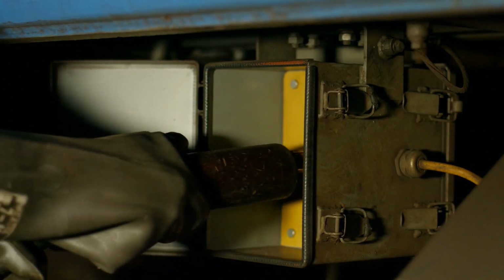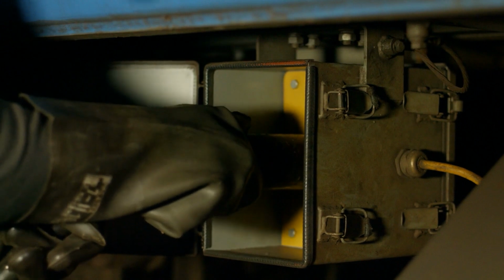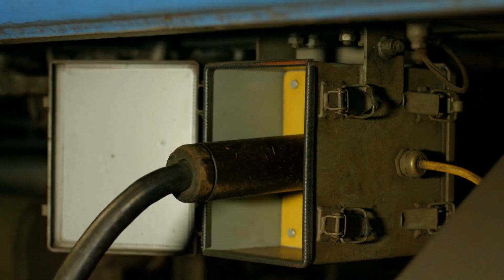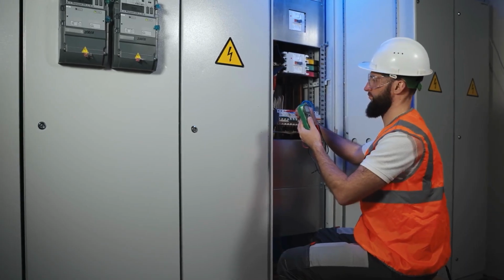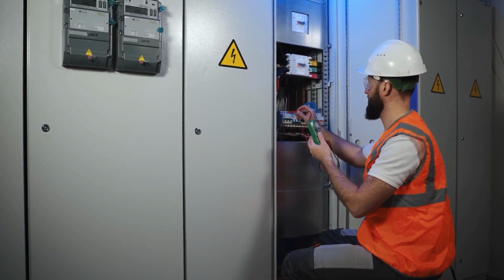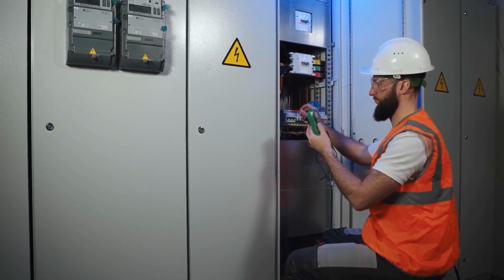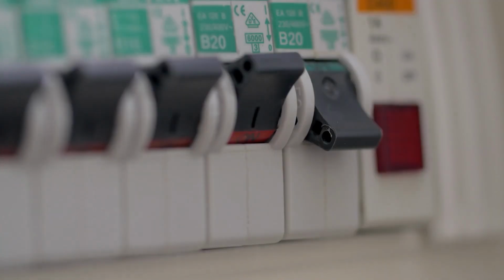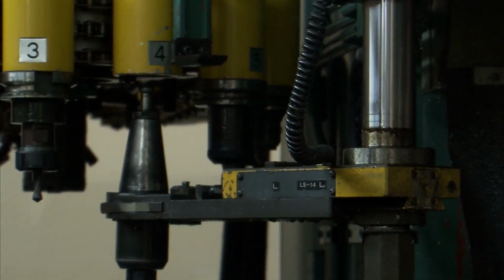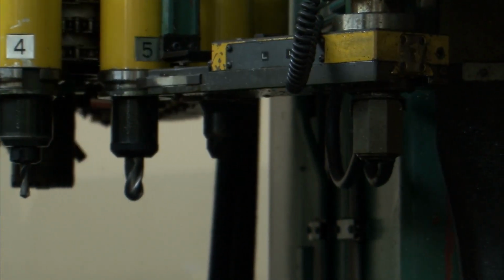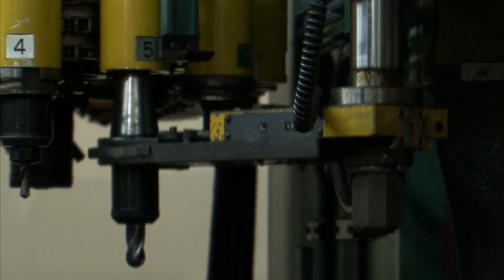Whenever any part of the body is exposed to these types of energy while servicing or maintaining equipment, lockout-tagout procedures must be followed. The primary way to prevent the release of hazardous energy during service and maintenance activities is by using energy-isolating devices such as manually operated circuit breakers, disconnect switches, line valves, and safety blocks. Lockout requires use of a lock or other lockout device to hold the energy-isolating device in a safe position to prevent machinery from becoming re-energized.